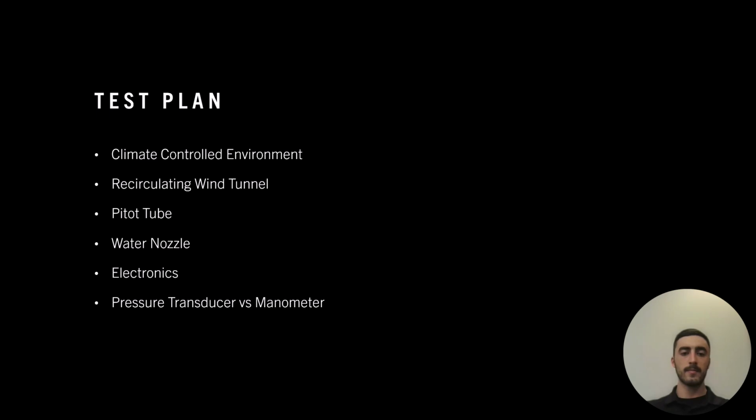The pitot tube was then inserted through a hole in the top of the duct and oriented so that it faced the airflow. For our water nozzle, a spoon head was attached to the end of a brass fitting with a small hole drilled into the top. This laminar stream exerted by the drilled hole hits the spoon and disperses the water across the surface of the pitot tube. The spoon atomizer was installed a few inches upstream of the pitot tube, just far enough so that ice formation was possible. The brass fitting was connected to a water tube that was powered by the Arduino.